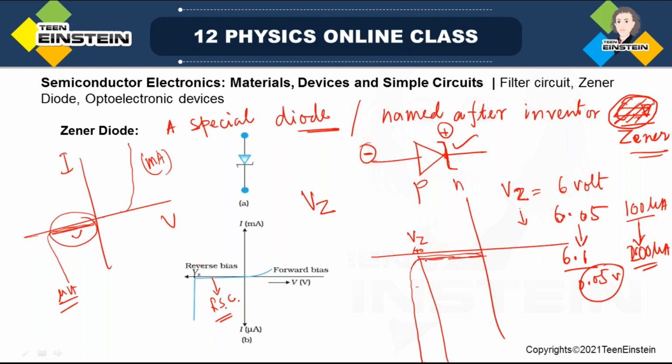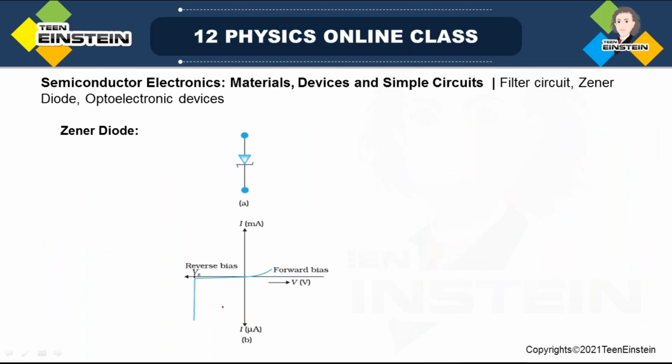After increasing voltage, it will increase the current, and the change in the current will obviously be much more than earlier. But in case of the Zener diode, you look here, almost the voltage is not changing. In normal cases, the voltage changes up to here, this much change is there. But see, the Zener voltage is almost constant, but the current is changing like anything. Okay, look, I'll clean everything and show you here.